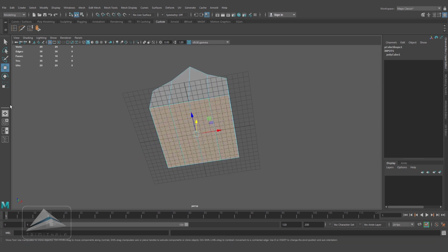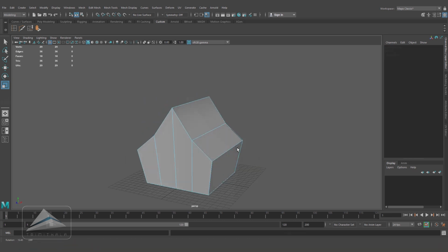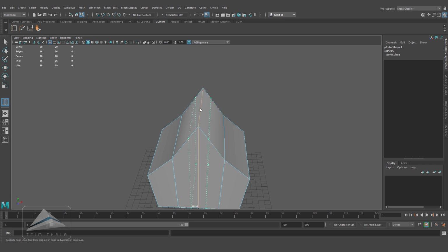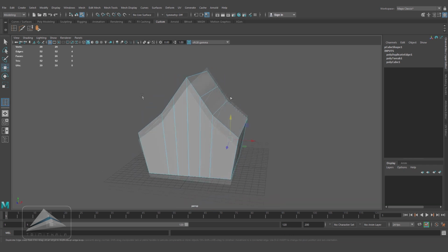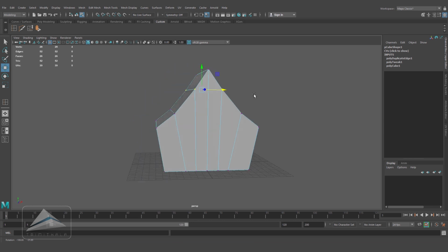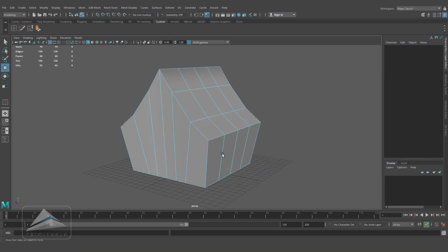Selecting the bottom faces and decreasing it just to get a proportion. Now going to the mesh tool and selecting offset edge loop tool and giving 2 edge loops at a similar distance. Now going to the side view and adjusting the vertices, making both the sides an arc. Now inserting one more edge loop at the middle and taking the offset edge loop tool once again. As you can see, I have given 3 edge loops.